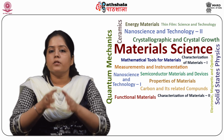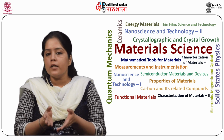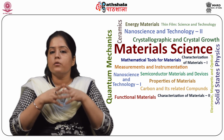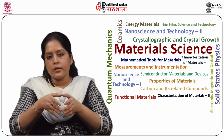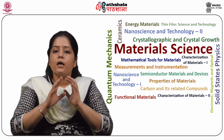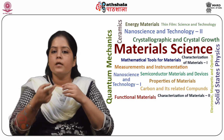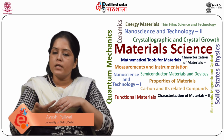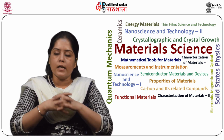Next, we also discussed the piezoelectric motors, basically the ultrasonic motors, rotary and linear motors, and traveling wave type motors. We also discussed the transducers in terms of audio frequency, ultrasonic and underwater, and the electrochemical transducers. Lastly, the other applications of piezoelectric materials include MEMS, piezoelectric transformers, piezoelectric dampers, vibrators, resonators, filters, and surface acoustic wave devices. They have been discussed in detail.